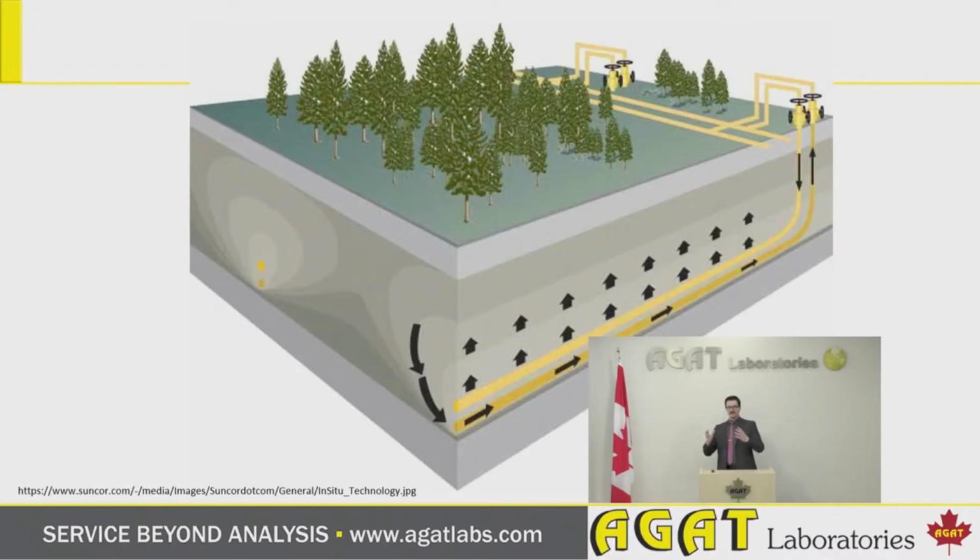Now, the steam is going to interact with the bitumen in the reservoir as it floods that heat into the reservoir, lowering the viscosity of the bitumen, which is naturally very, very viscous, does not want to flow, and that allows it to flow down under gravity to the lower of the two wells. This diagram does simplify things a little bit. For instance, we've got very little overburden visible in this diagram. Usually it's a couple of 100 meters thick, but also the structure in the reservoir is completely simplified. We're just showing the steam chamber's idealized shape here.